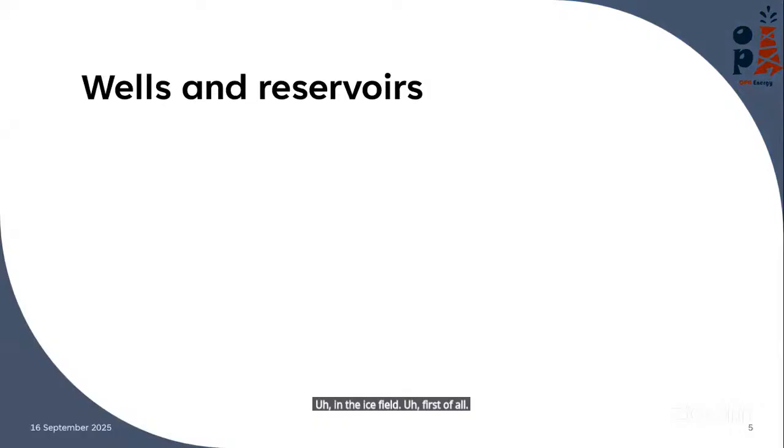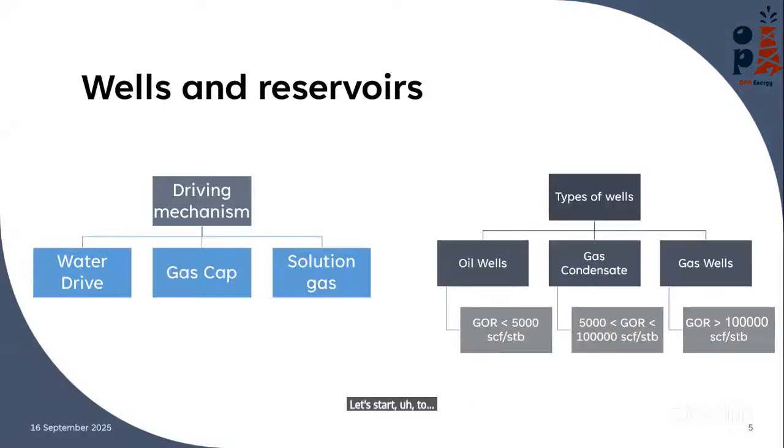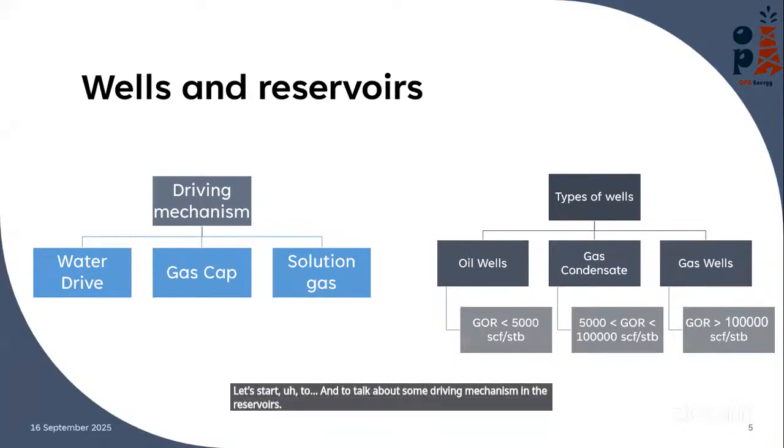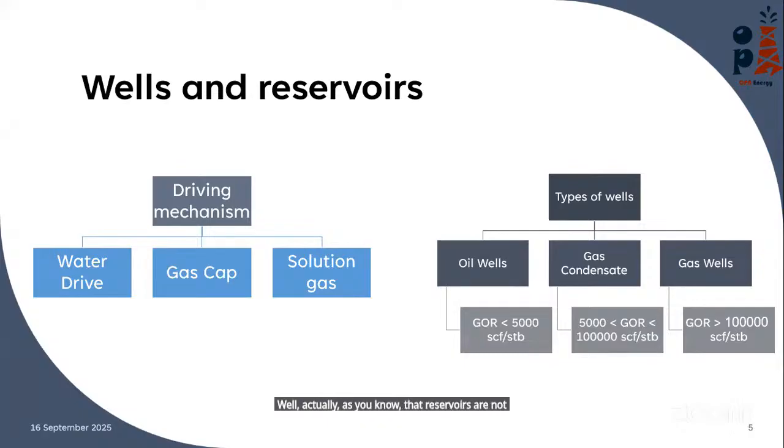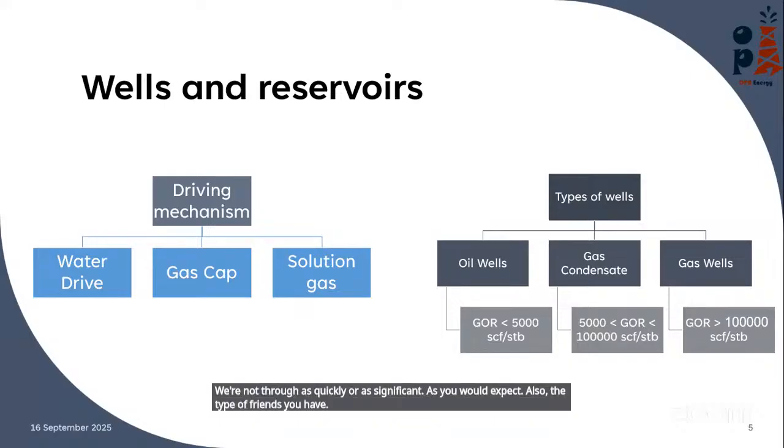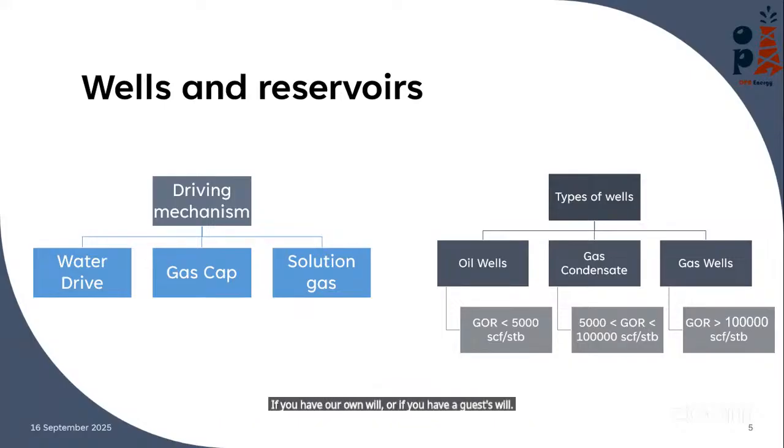First of all, let's talk about some driving mechanisms in the reservoirs. Actually, as you know, reservoirs are not created equal. The driving mechanism affects productivity significantly. If you have a water drive, your problems will be less than if you have a solution gas drive, because your pressure will not drop as quickly or as significantly as you would expect. Also, the type of wells you have: if you have an oil well, or a gas well, some problems will arise from gas condensate if you have this operation.